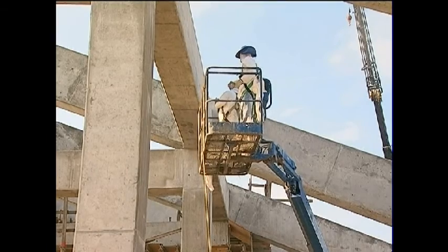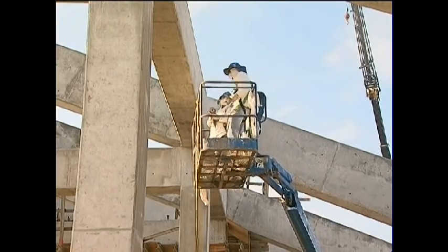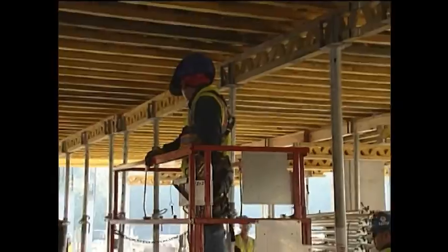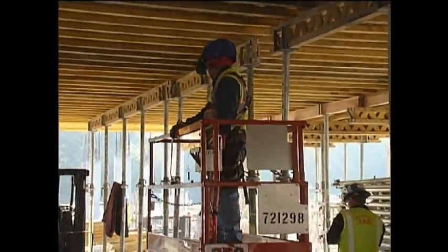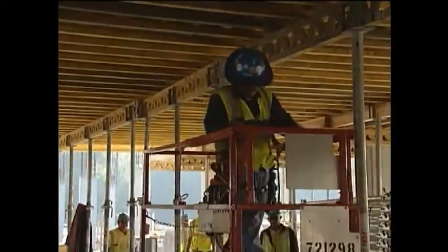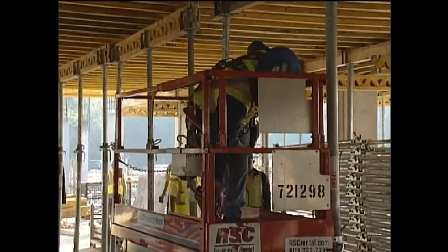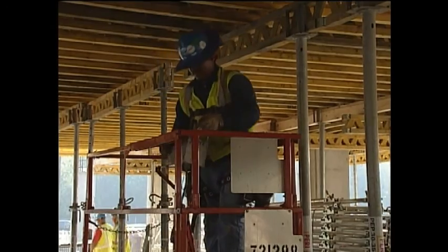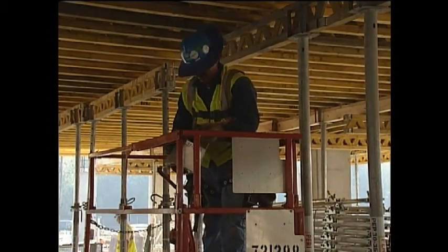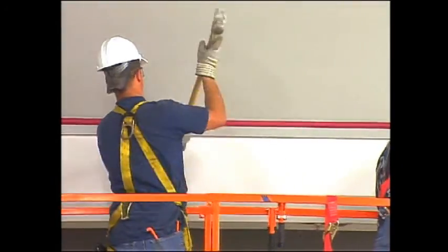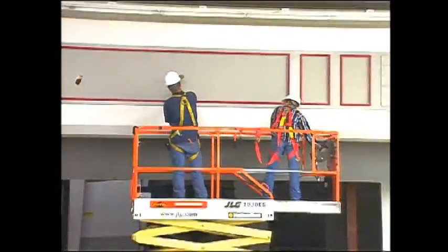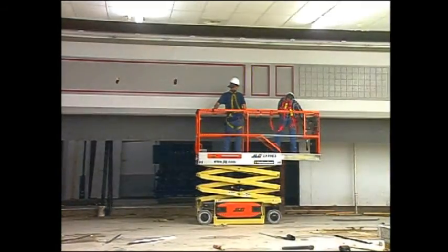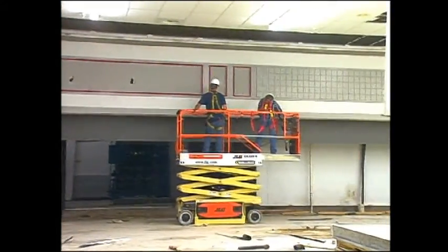Fall protection is required for all personnel that perform work on a lift, even if the lift is used according to manufacturer's guidelines and all safety precautions are followed. The chance of a fall is minimized. All scissor lifts require fall protection. Guardrails that are properly designed, maintained, and meet OSHA guardrail requirements are sufficient fall protection. If the guardrail does not meet OSHA standards, or if an employee leaves the safety of the work platform, then a personal fall arrest system utilizing a full body harness is required.